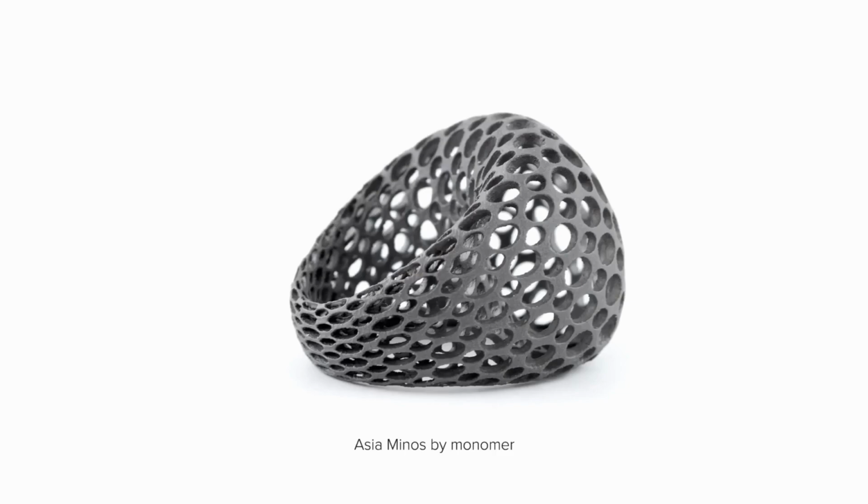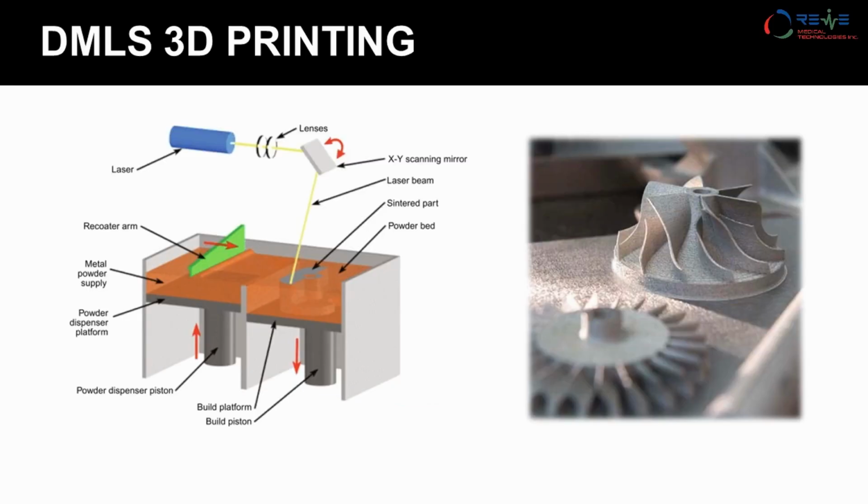And later on, you have to go into electro polishing to get that sort of finishing out of these parts. So again, same principle as SLS, slightly more refined mechanism because it's got metal in it. The powder is ensured to be very, very refined. The more refined the powder is, the smaller the granules are, the better it does. If the weight of the granules is increased, the parts start failing. So they have to ensure a specific size of granule is used. If you increase the size, then it fails later on.